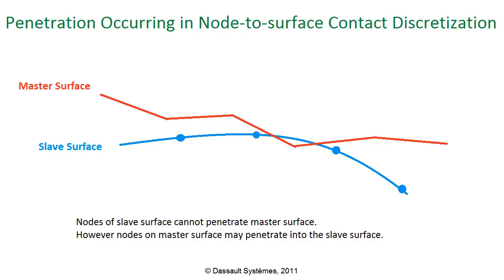The surface-to-surface contact formulation, on the other hand, considers the shape of both the master and slave surfaces in the region of contact, and enforces the contact conditions in an average sense over regions near the slave nodes rather than on individual slave nodes alone. Large penetrations of master nodes into the slave surface do not occur with this discretization. Hence the choice of master and slave is not as important, but the same surface selection guidelines as node-to-surface discretization should be followed where possible.